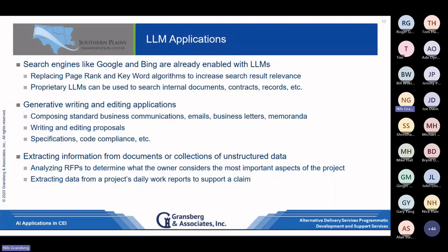I'm working with a client right now where we're taking a prescriptive design and converting it into an RFP for a design build project. Which means we're only going to be prescriptive on the things they absolutely have, and everything that's not, I'm going to use performance language for. I'm going to specify performance.